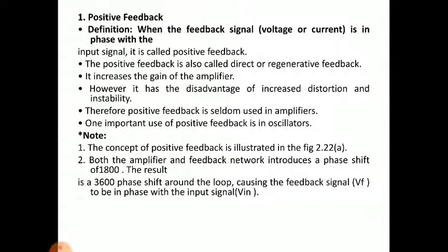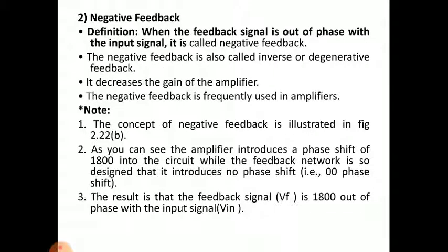The result is a 360 degrees phase shift around the loop, causing the feedback signal Vf to be in phase with the input signal. Next is the negative feedback.